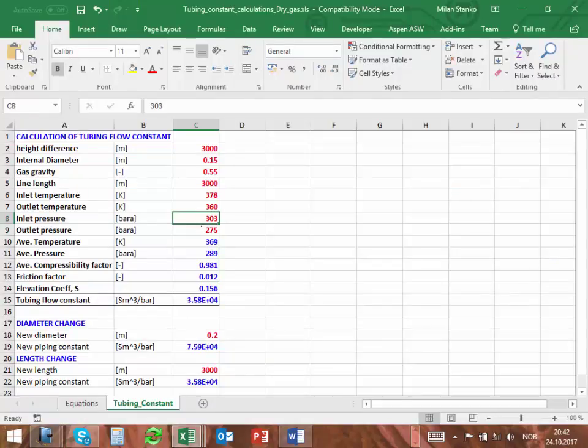But you will see, if we assume these two numbers, there will be a pressure drop. For example, to start with, I can use reservoir pressure. And this pressure at the top, I have it. That's part of the calculation. And then I calculate my CT, and after I run my computations, I can see if that was a good assumption or not, and eventually change the CT. Yes or not? More or less? Comme ci, comme ça? Mais ou menos?